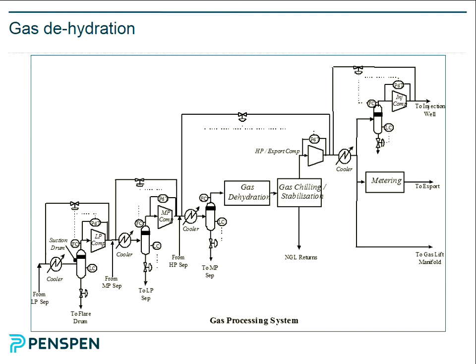And H2S, there are various ways. One way is to use a chemical scavenging agent. Sulfurite is one, a trade name. So you've got inlet sour gas, you put it through the chemical, and you get sweet gas coming out. And there'll be a way of either replacing the chemical or cleaning the chemical using another process.